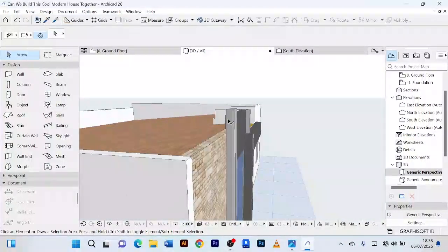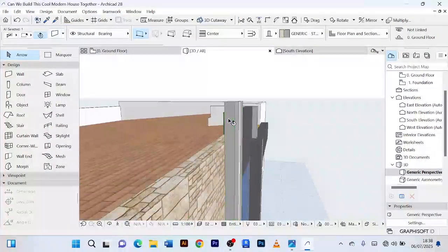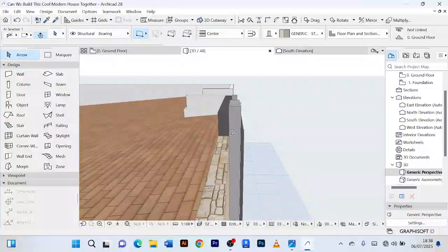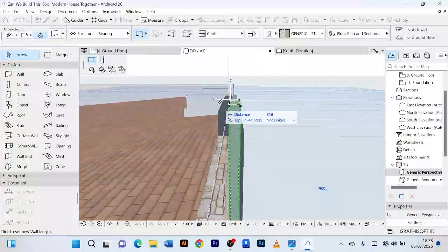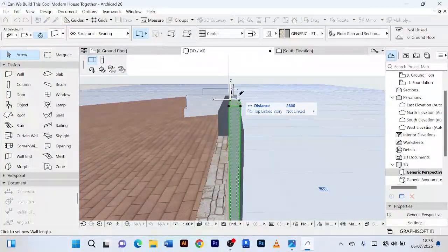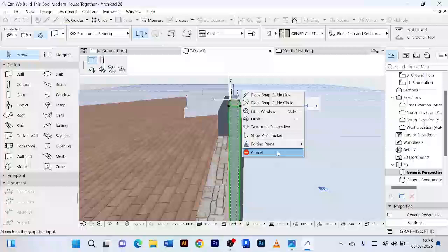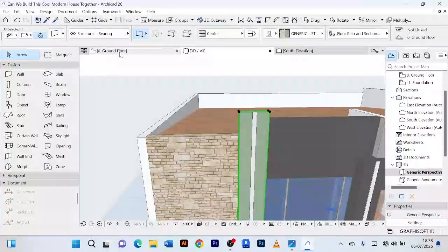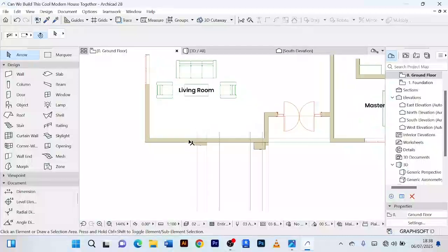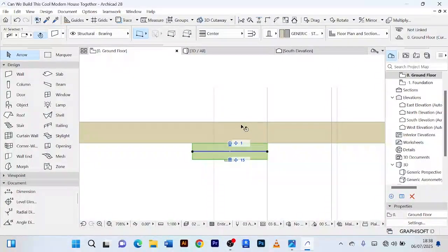And then for this wall here, I want to increase the thickness. I want the thickness to enter inside here. If I come here, I can select this type of stretch that can stretch it this side. However, I'm seeing it is giving us trouble, but let's go to the ground floor. It is this wall here. So if I want to make it